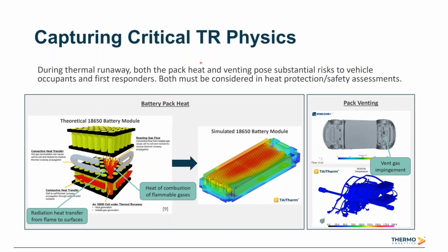Okay, so now we're focused on the heat protection and safety workflow. As always, it's important that we're capturing all of the critical physics of the system. In this case, for thermal runaway, we need to capture all of the critical heat sources and also the critical heat transfer mechanisms. So the key ones here, we have the battery pack heat. So we have a fire occurring inside our pack, so it's getting very hot.